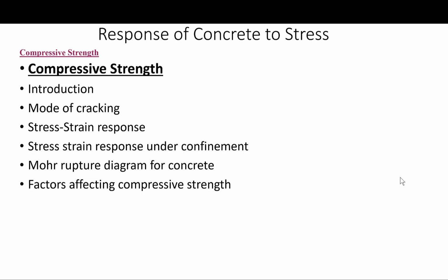Due to the differences in material properties, the lateral strain due to Poisson's effects is greater for the concrete than for the end platens, resulting in friction between the test specimen and the platens, which places the end regions of the specimen in somewhat of a triaxial compression, as you will see in a bit.